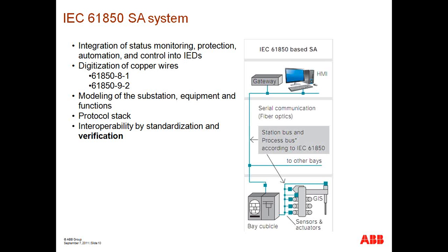That information is in turn published on the process bus network, which again is really referred to as the network that's close to the apparatus or the primary equipment. It's also envisioned that within the process bus you're going to have binary signals to, let's say, trip the breaker, if the breaker had the intelligence of receiving a GOOSE message to trip or to close. So when we talk about process bus, we're not exclusively talking about analog signals. We're just referring to the network that is close to the primary apparatus.